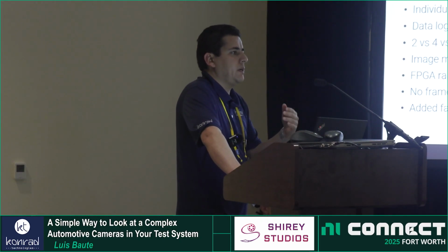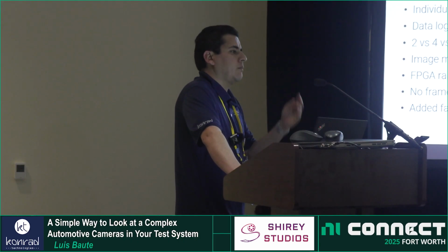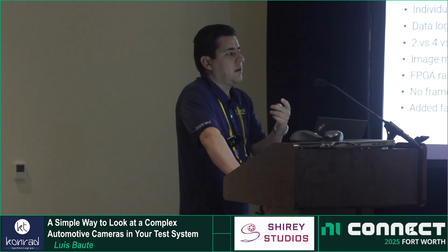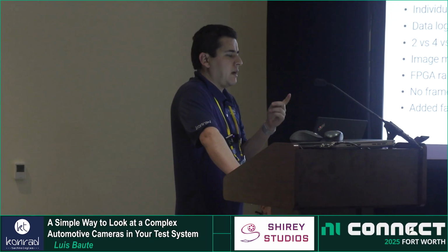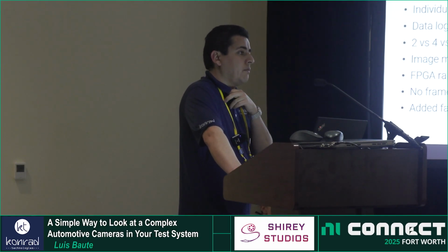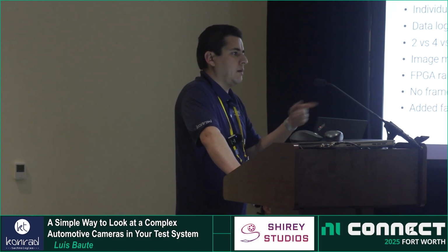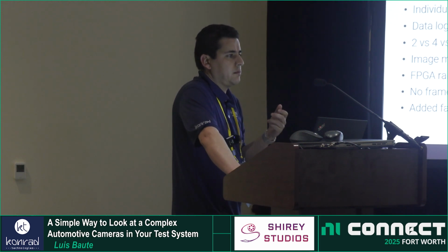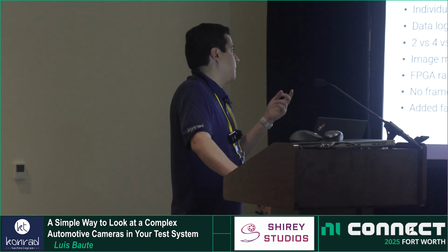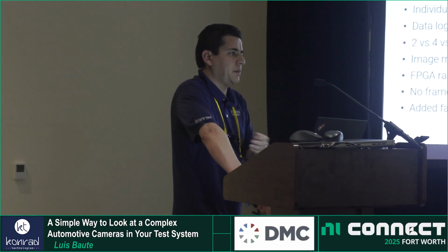So that's the reason why we needed all of them on board, because if not, we would need to stop the FPGA. And also, these cameras have one thing, which is when they get powered off, they lose the programming. So every time you power cycle, you need to program them. Or also when you disconnect, that happens too. So for these, we needed to have all the channels working without needing to stop the FPGA.